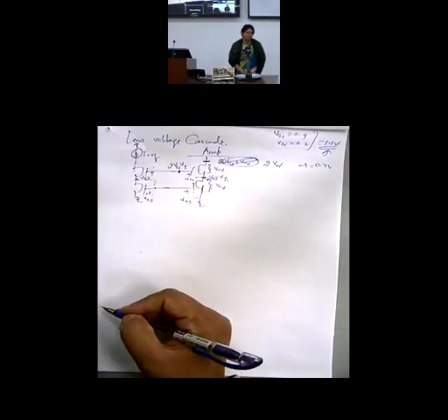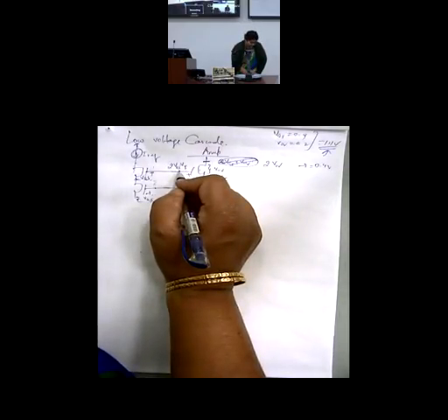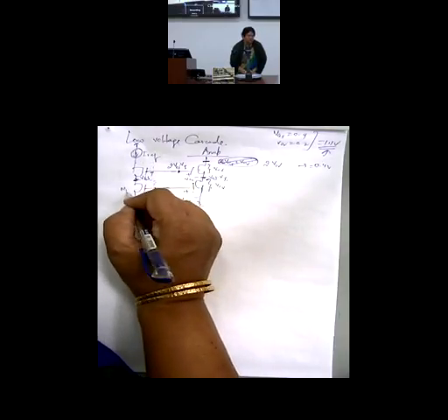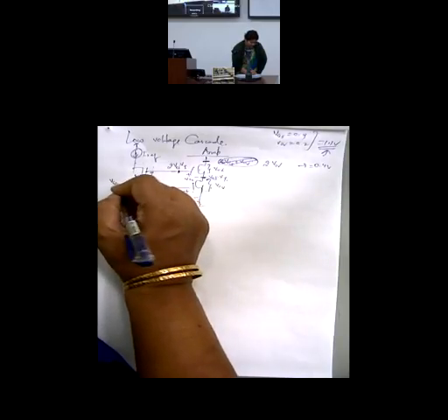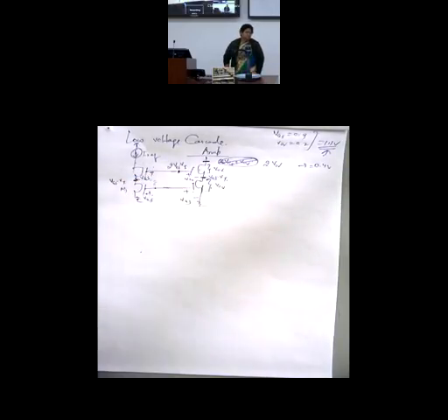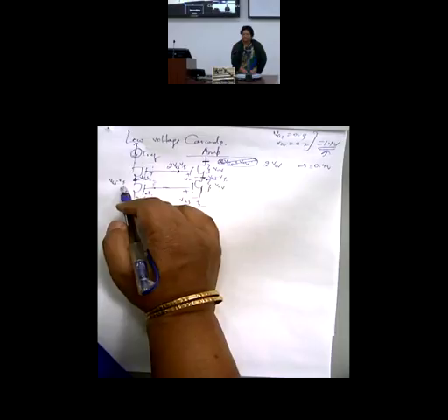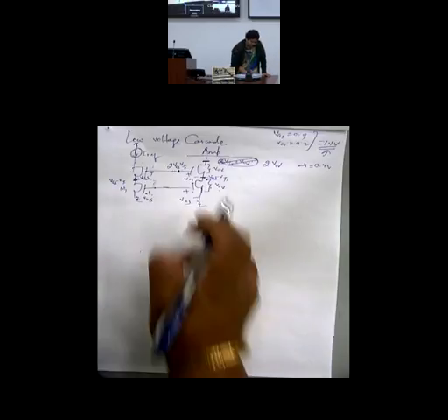I am assuming all 4 transistors matched. So now this is 2 VGS minus VT. And minimum I require here for this lower transistor M1 to be in saturation is 1 V overdrive. So it is VGS minus VT. Because 2 VGS minus VT here, 1 VGS down, this will automatically come to VGS minus VT. So here we make a connection.